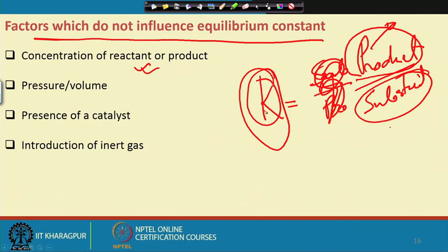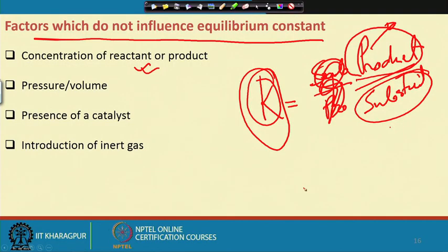An example is the ethanol fermentation process. Ethanol is a volatile component. Under vacuum, at a low temperature, we can volatilize the ethanol. If you take out the ethanol, more substrate will be converted to ethanol and the productivity of the system will increase.